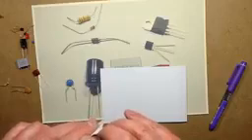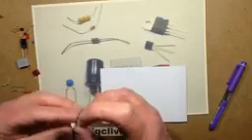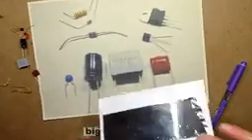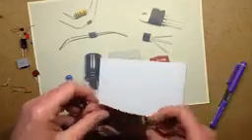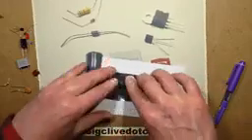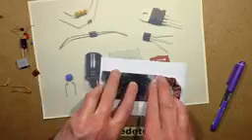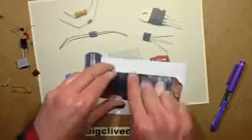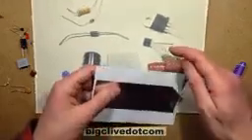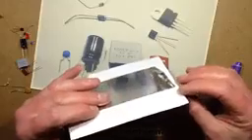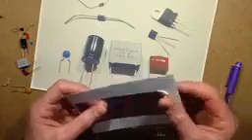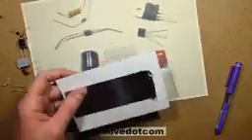And this is the physical construction that's used throughout all capacitors. They're all pretty much like this, but not using cardboard and aluminium foil. So let's get that pretty much as close to the other one in alignment as possible. And the 2 factors determining the capacitance here are the area of metallization that's in parallel with the other one, and how thick the insulator is in between. And you'd think, this card is very thin, so it's going to be a modestly high value of capacitance, but that's not true. This is not going to be a high value of capacitance at all.